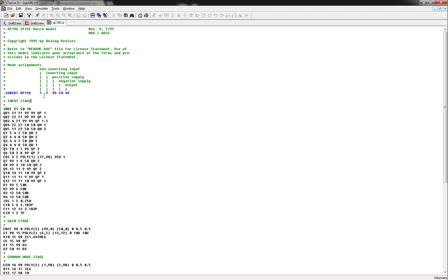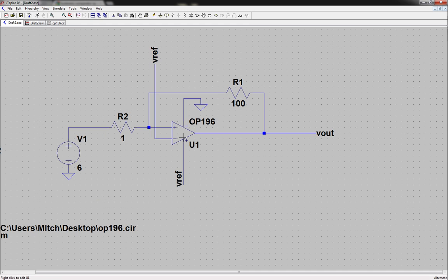So if you get a different MOSFET where maybe the first pin is drain and then gate and then source, but then you get another manufacturer that goes gate, drain, source, well, then where you've placed your gate pin in your symbol won't be in the right spot. It'll be on the drain or something, because the 2 models are different. So always make sure your pins correspond to where the pins are on the symbol. If they are, then you can just straight away use the symbol.